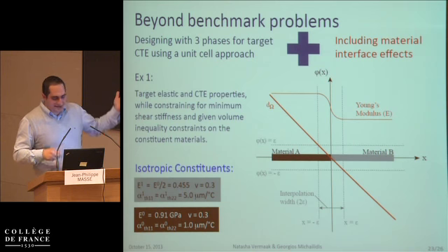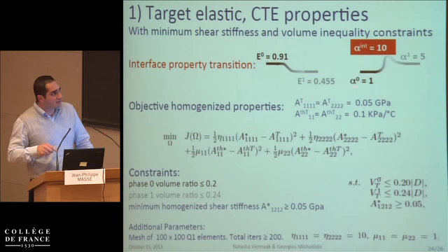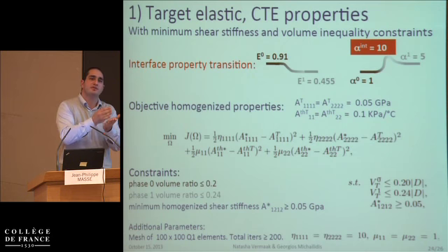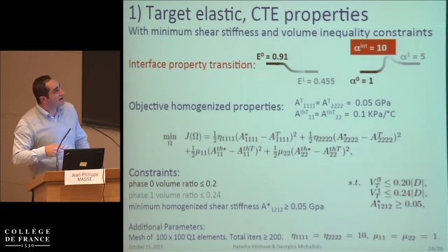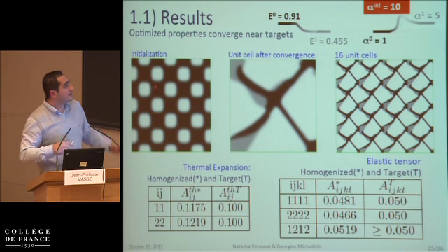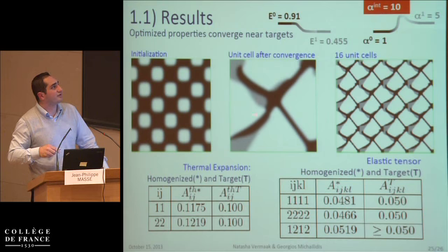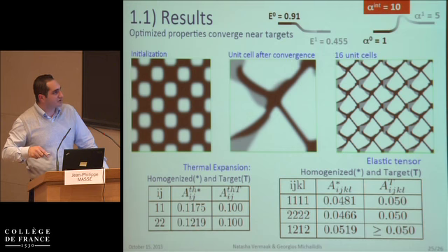So we take the last example, and this time we consider that for the thermal strain coefficient there is a bump in the intermediate interface of the two materials. This is the profile of the Young modulus, and this is the profile of the thermal strain coefficients. The problem is the same as previously, and starting from a guess shape, we converge to an optimized shape that has a much different form than the previous. Again, the homogenized coefficients are close to the target coefficients, so we are satisfied.